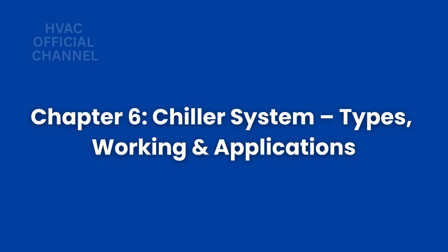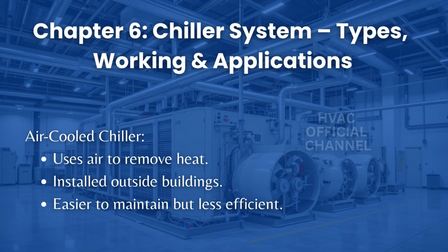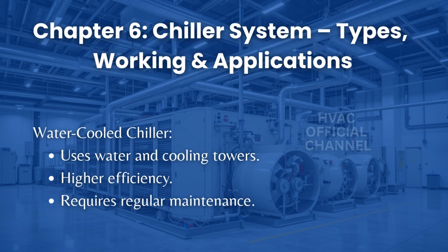Chapter 6. Chiller System. Types, working, and applications. Air-cooled chiller. Uses air to remove heat, installed outside buildings. Easier to maintain but less efficient. Water-cooled chiller. Uses water and cooling towers. Higher efficiency. Requires regular maintenance.